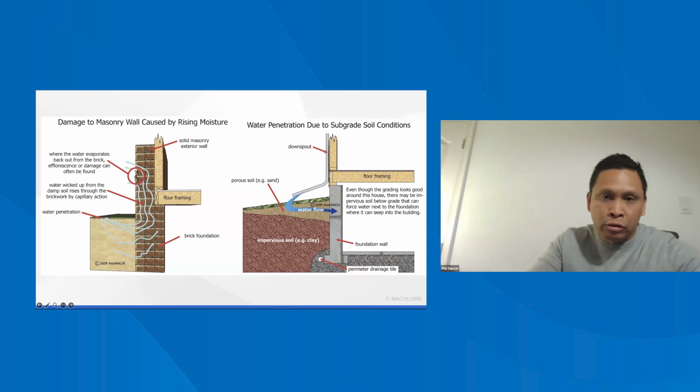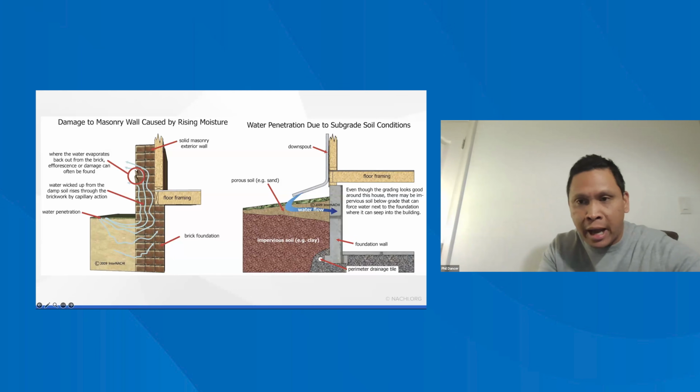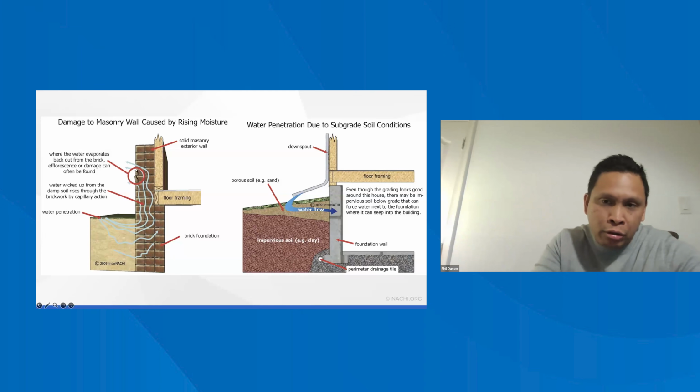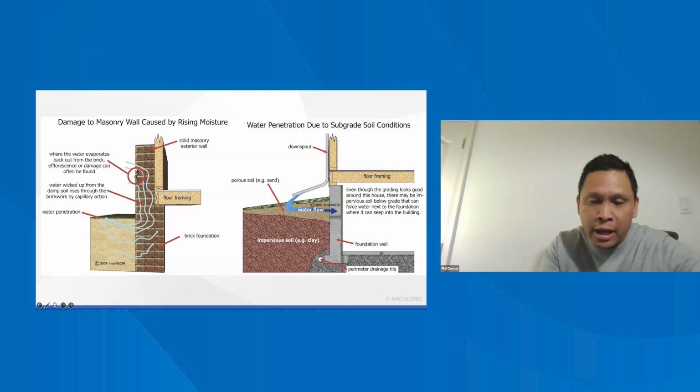Oftentimes builders will just wrap that in some type of flashing tape to act as the capillary break.